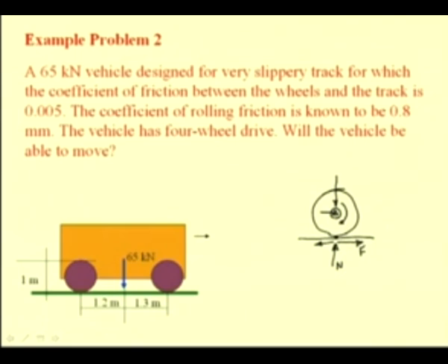and this developed force for traction should overcome this rolling resistance. So, we have to ultimately see that the rolling resistance has to be less than the maximum available friction on the track. If this condition is satisfied, the wheel will be able to propel forward.